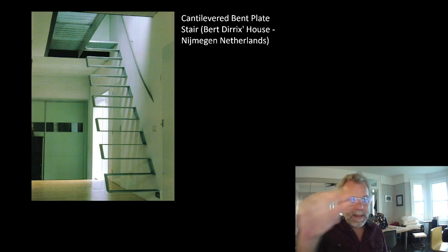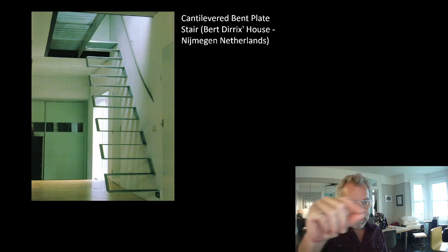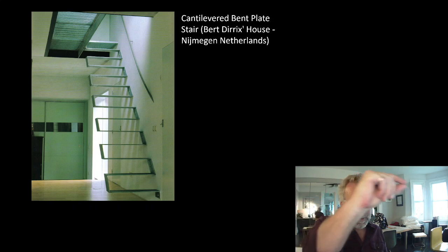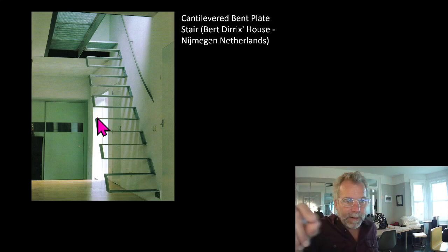So instead of doing this, the stair is forced to do this. It bends in an S shape because the interconnecting plate prevents it from rotating at the end. That simple move doubles the stiffness of the stair. Well, no, dramatically, probably increases it by 4 or 8-fold, by forcing it to bend into an S shape as opposed to a simple cantilever.